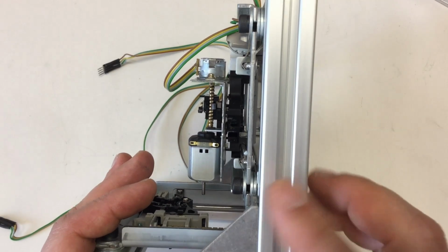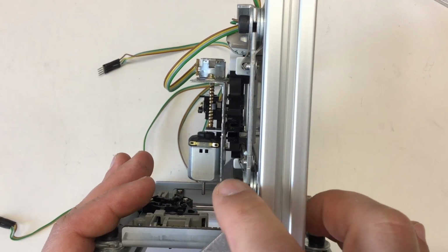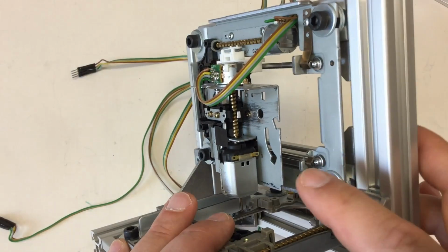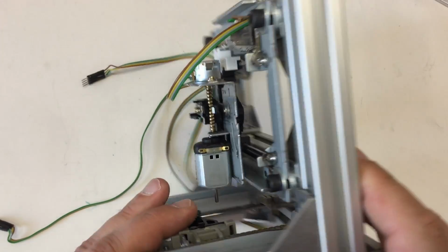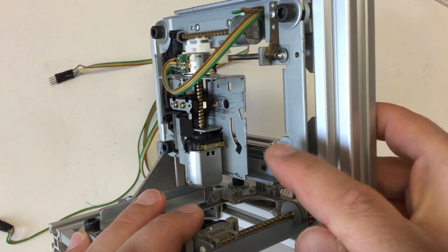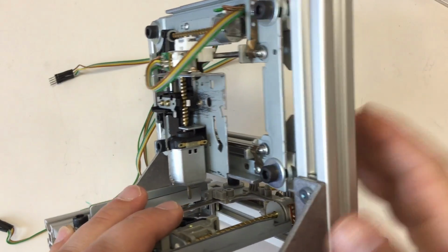First is the distance between the spindle axis, or the tool center, to your upper and lower bearings. And second, the distance between your upper and lower bearing. That's all we need for the moment.